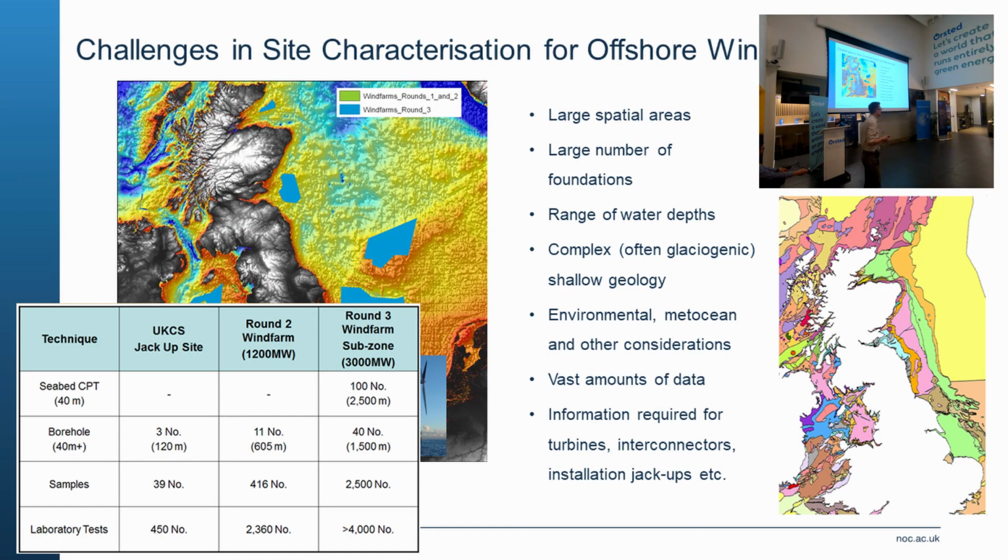Offshore wind, particularly looking at Round 3, there's a number of reasons why a ground model approach is warranted and useful. Partly it's because we're looking at unprecedented large spatial areas with lots of foundations, challenging infrastructure, interconnector arrays, a whole range of water depths. Maybe you need to consider multiple different foundation concepts. And very complex geology, particularly in the North Sea, in an area that has experienced previous phases of glaciation and deglaciation. Some areas which are now submarine were formerly, during previous sea level stands, actually exposed, and may have been loaded by significant amounts of ice. So laterally and vertically, soil conditions can be very variable.